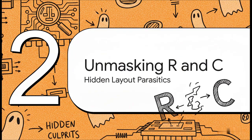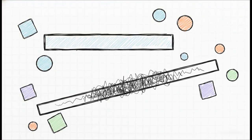That's where your nice straight wire suddenly decides to act like a tiny, totally unwanted magnetic coil. Moving right along to Section 2, Unmasking Resistance and Capacitance. Okay, so when we talk about parasitic resistance, we are looking straight at the friction in our electrical pipes. Every single time you draw a longer wire, you are actively cranking up that parasitic resistance. Remember, resistance is length divided by cross-sectional area, so longer equals more resistance, wider equals less.